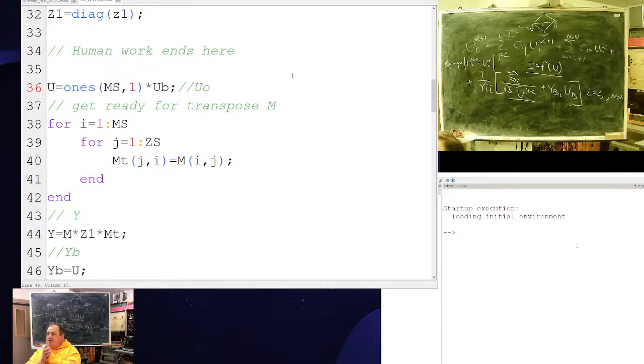See, voltages of such network, I don't think they will be too far from base node voltage. It's a starting point. I will go sequentially towards the real solution. So to increase performance, I will start from base node voltage. Not from zeros, but from base node voltage.